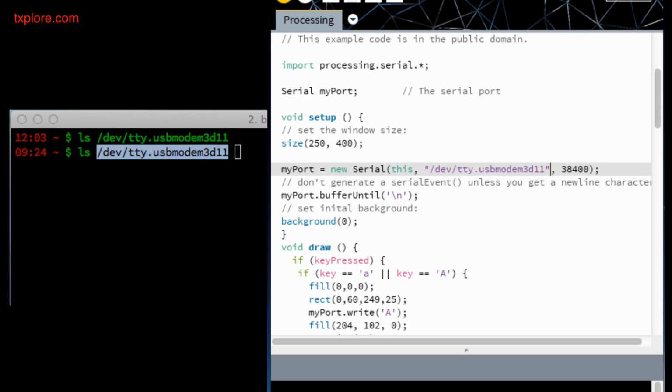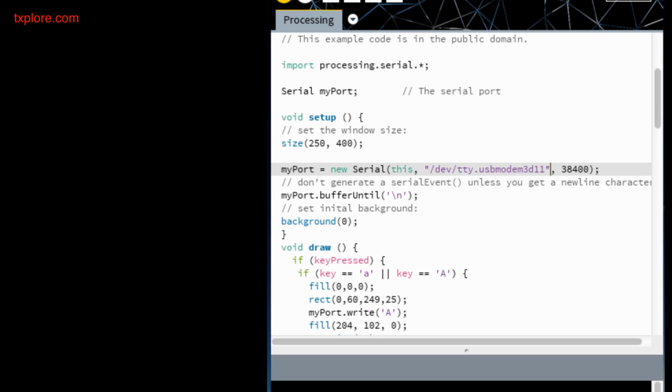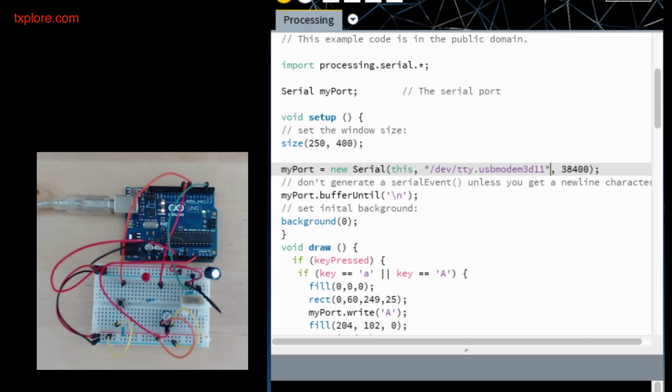Okay, so next thing to consider is in my setup now I have an Arduino and I've got my computer running the processing sketch, and I want them to interact. The Arduino is going to be getting readings from its sensors, especially the DHT22, but I've got a rotary potentiometer here and a button. So I wanted to collect values from these three things and then send them off to the processing sketch.